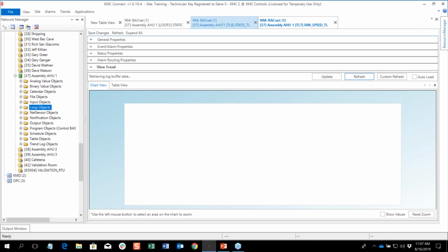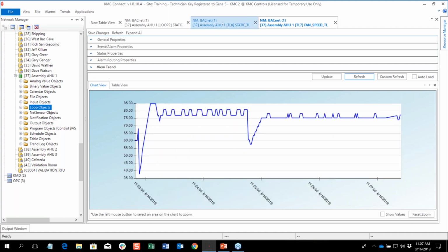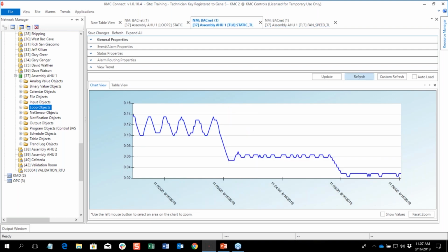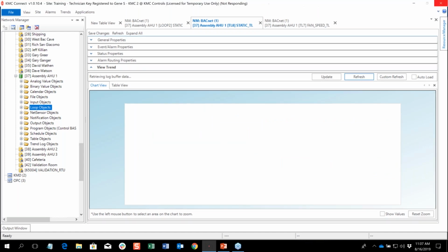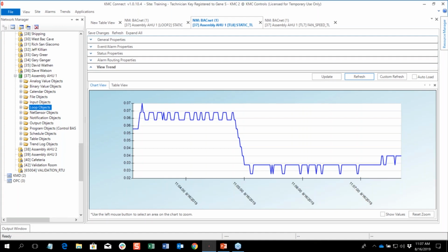With proportional only, remember that that's a linear gain off of my error. The only way that I'm going to have a PID loop output at all with a proportional value is if I have an error. If we think of a room temperature that's tracking out of set point, the farther my error gets from set point, the more loop output I'm going to get until that loop rises to a point where my error stops and my error becomes stable.